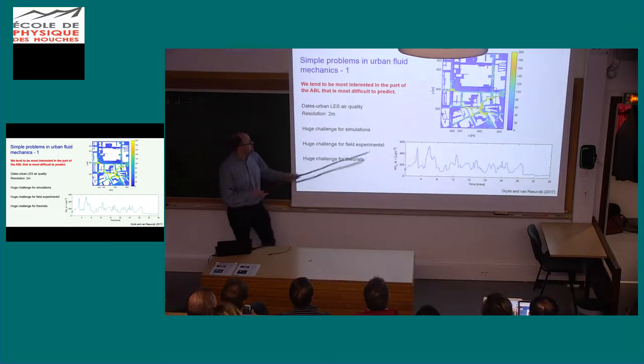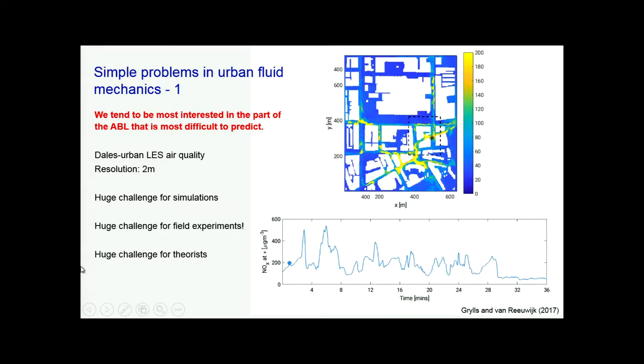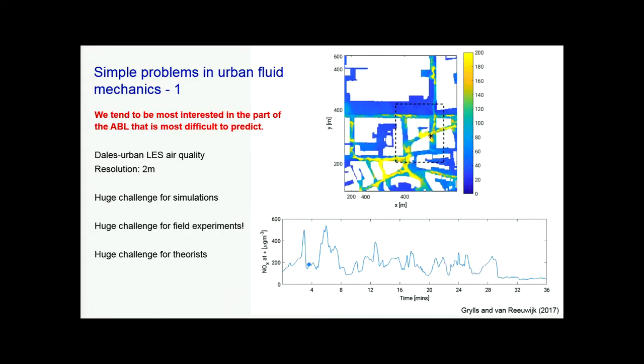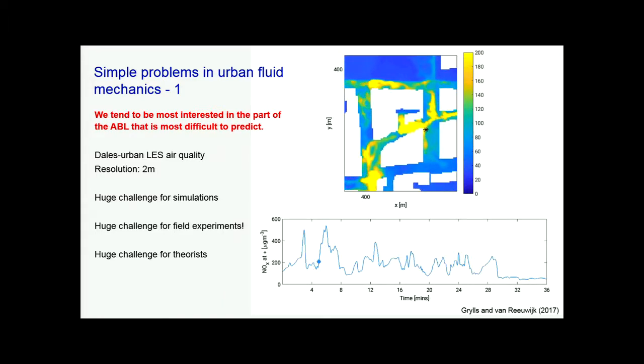It's a wind from the southwest, I should say. So it's a mild wind, 2.5 meters per second. Yeah, so a nice summery day. So you clearly see that in general, on the main streets, the wind kind of transports all the pollution in this direction. But at this corner, something very interesting happens. So you've got the wind coming over the buildings. You're going to get recirculation, and actually you've got a lot of transport from this main road into this area here, and you get peaks here of up to 400 micrograms per cubic meter, which is about twice the allowed hourly average, right? So you're exposed to huge spikes.